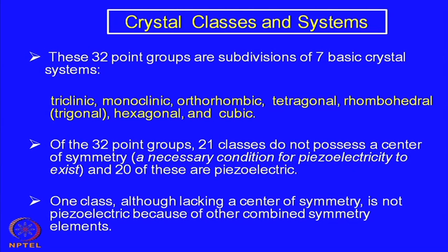Okay. So, any crystal class or any crystal structure having a center of symmetry will not have piezoelectric property, and that is a very important statement that has to be remembered all the time. Out of 32 point groups or crystal classes, 21 do not possess a center of symmetry, and they are the crystals in which piezoelectricity can be observed.